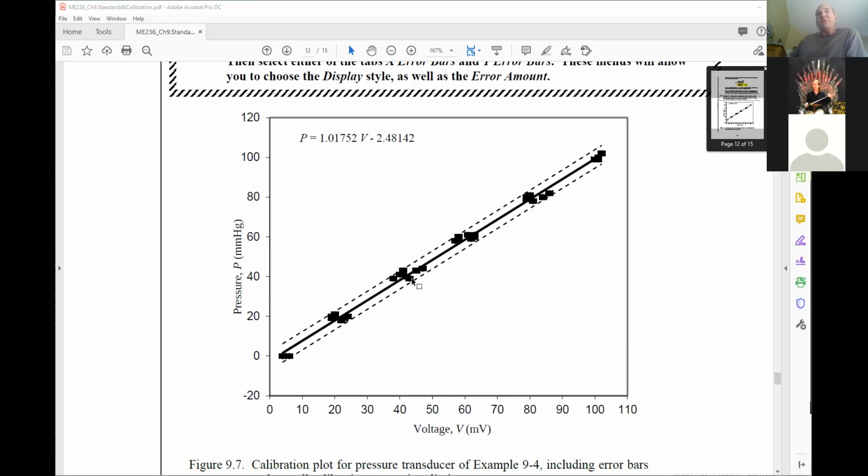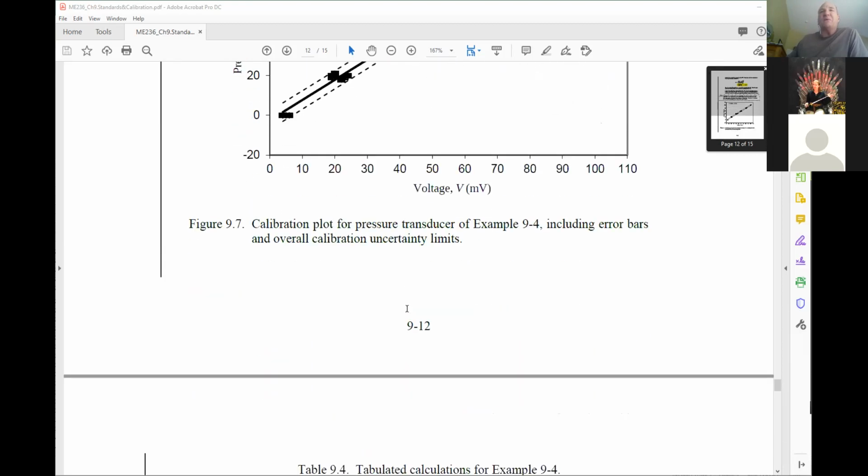But what you are going to find when you plot the data, because the strain gauge is really accurate, is that the lines are almost going to be on top of one another, and it won't look as nicely dispersed as this. To combat that, you'll plot your normal plot that'll look like this, but you'll also plot a second plot where you go from full scale 30 to 40 millivolts, and then full scale maybe 20 to 30. In this case it'd be pressure, or you'll go full scale between say 100 and 200 grams. All you're doing is basically expanding the graph, so you'll be able to see that focused in part.